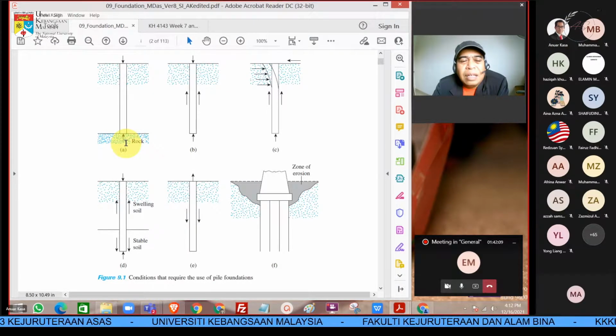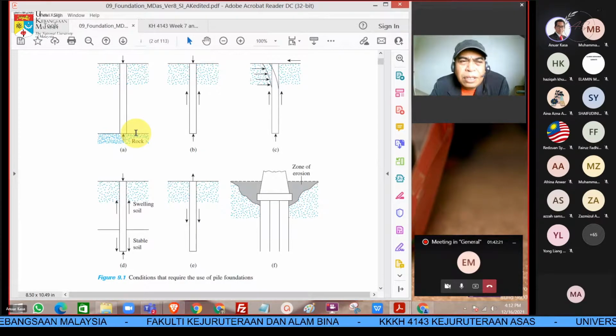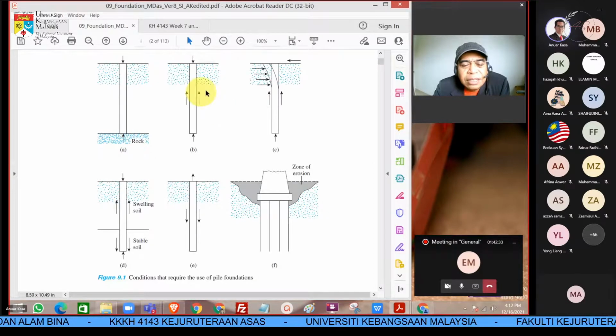And yeah, that is a normal case. Normally we go until the rock level. But if the rock level is too deep, as if we cannot find the rock, then we need to consider the skin friction. For example, for case B here. Definitely there is a small area at the tip that also supports the load, but it's not so much.